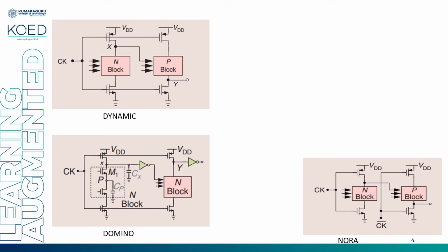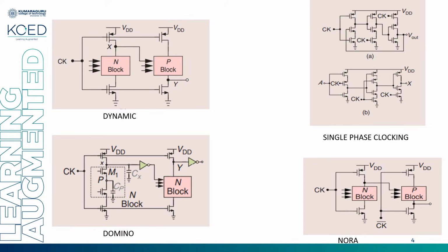They had their own advantages and disadvantages. So using all these they designed, and finally they came out with single phase clocking to go for a latch design and a frequency divider. Okay, so there it started. So first we learned how to design a single phase positive latch. Okay, so this concept TSPC we are learning as a dynamic logic style to design dynamic circuits. The very basic dynamic circuit will start now, the latch. So first we'll design a positive latch using single phase clocking.